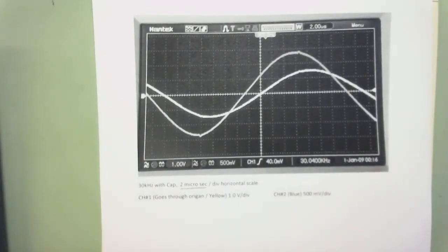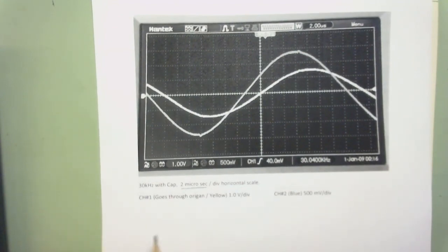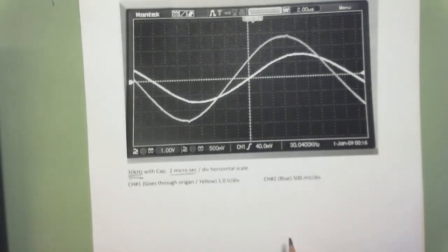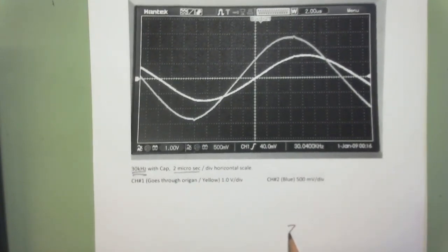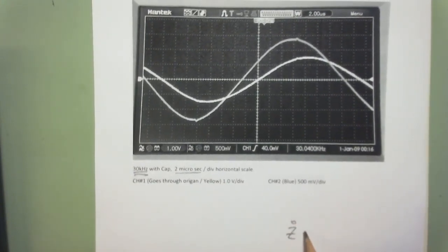This one, then we go back to the capacitor, and we're running a higher frequency. The one thing that I would caution you on this, I went through these numbers already. When I got down to my impedance here, I'm not going to spoil the surprise too much for you, but I got a small negative number, minus j, and then this 1 over omega C term.